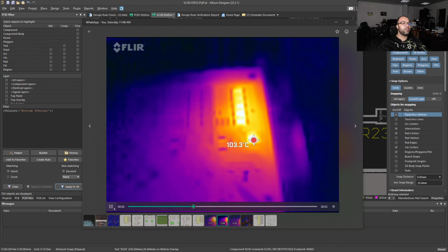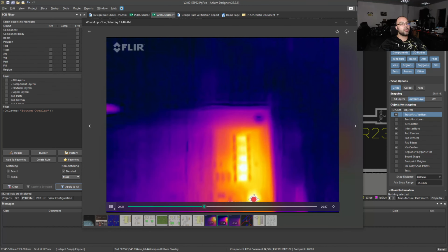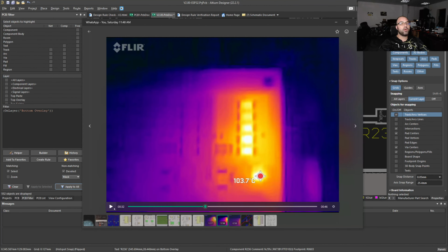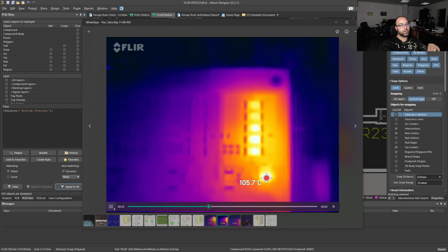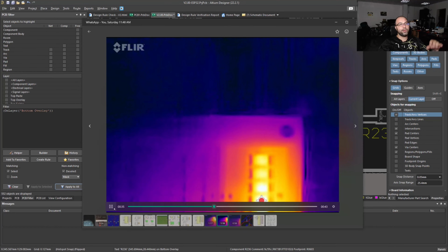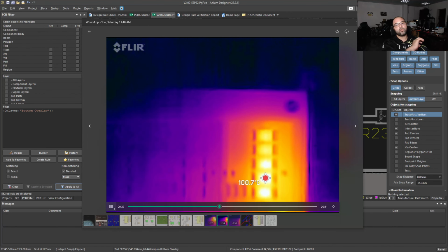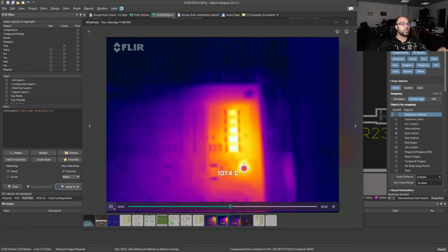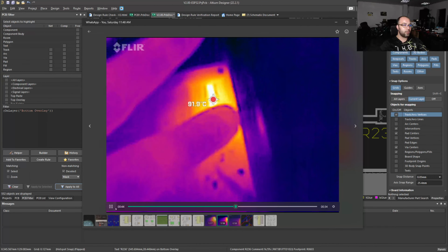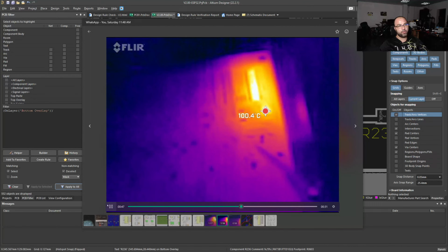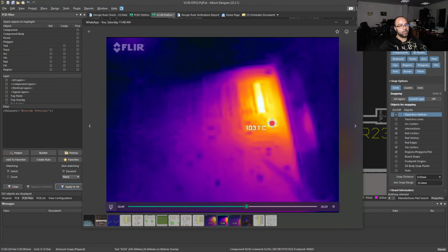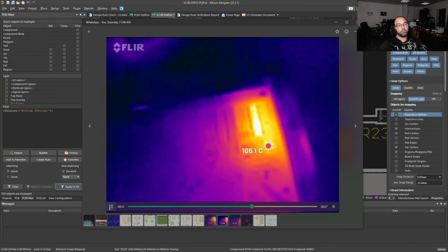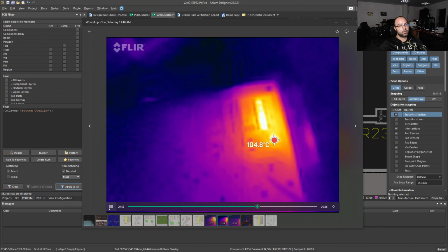I looked for different MOSFETs, but this one is the right one for the design we have, because we're using low voltage gate control, and others use higher voltage, 8, 12 volts, and we have to change the design to accommodate such voltage for gate control. But for now it works fine, no issues with it. I could not burn this resistor so far.